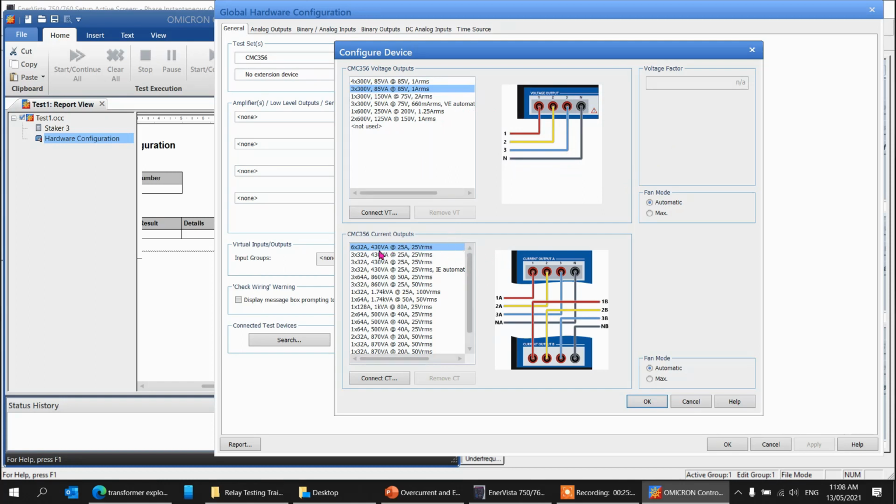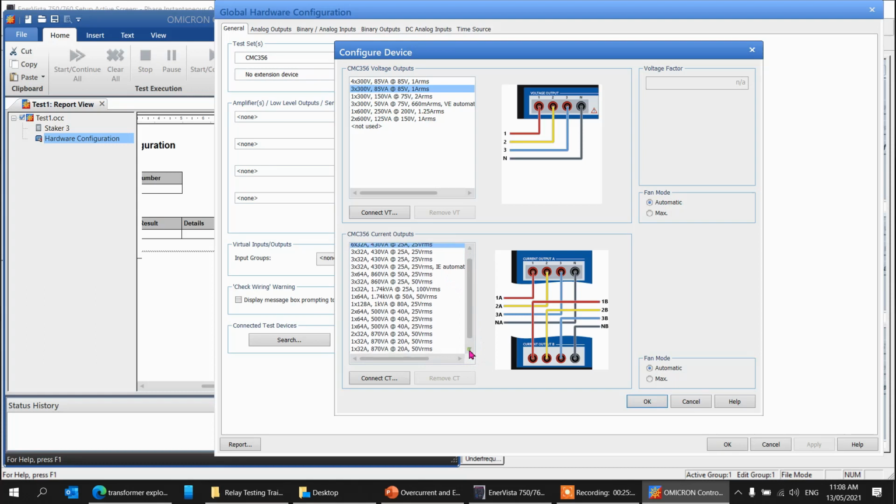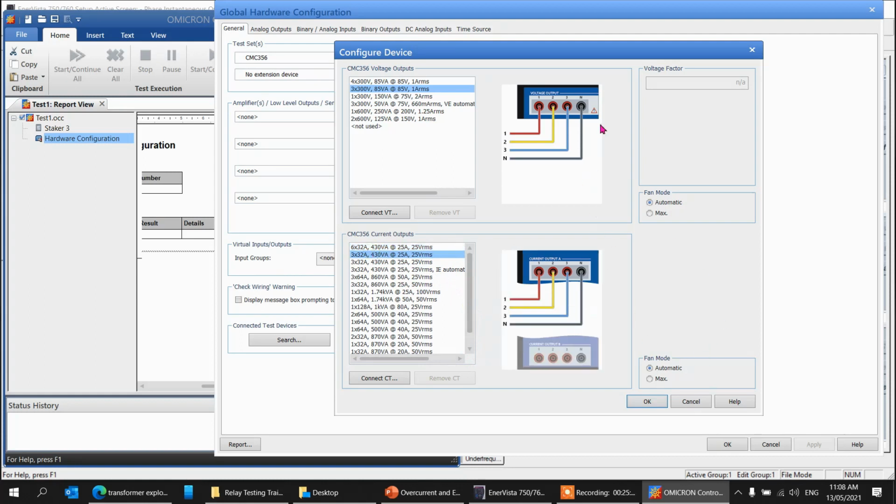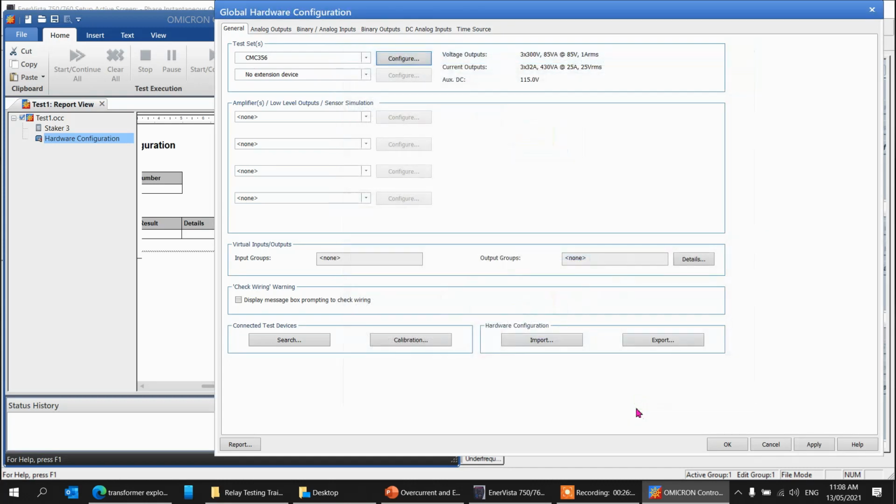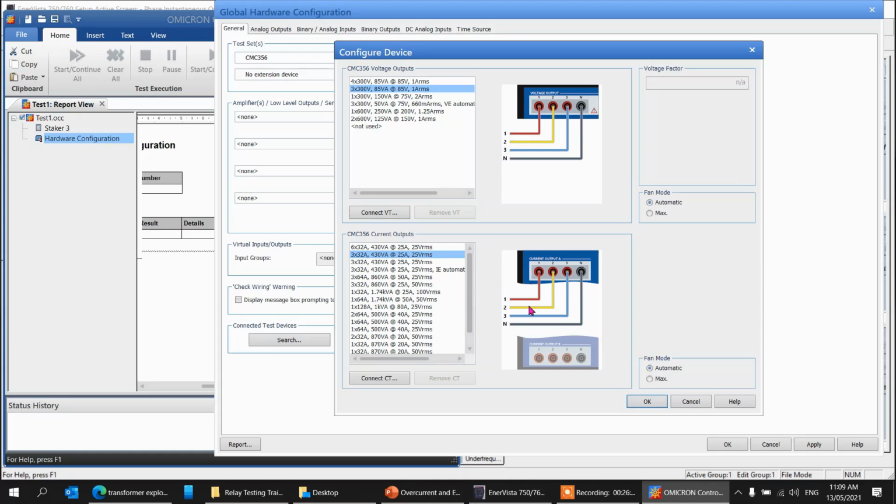And this one, we can select probably this one here, 3-phase. So that's what we want, isn't it? Based on the drawing and the schematic that we have, sometimes we remove this because sometimes there is no voltage protection like frequency or over/under. Since we have frequency, we need this voltage. And 3-phase current, 3-phase voltage, that will do the work, isn't it? So you have to analyze everything based on the documents available to you. Yeah, I always use 3-phase voltage and current for mine because as part of our test, we need to verify also the metering. Metering, yeah.